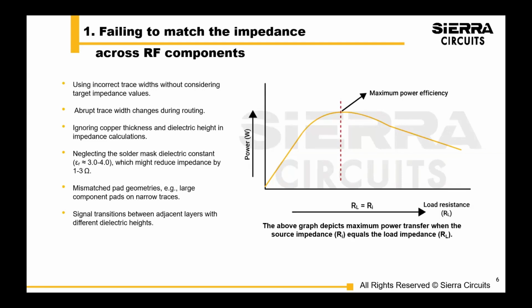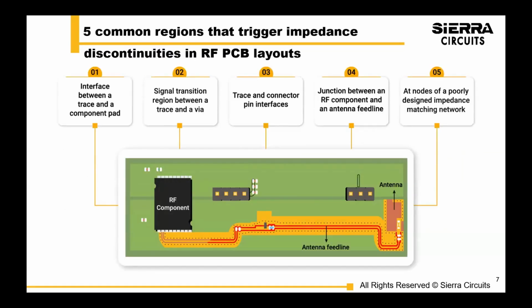So if you get a cross section of your board after manufacturing, you can understand your model a little bit better. What was the thickness of the solder mask and the copper weights and the dielectric pressed-out thicknesses, and you can feed that back into your own models and information, leading to continuous improvement. I think that's a key point here, not necessarily mentioned. So, yeah, these are some of the key things.